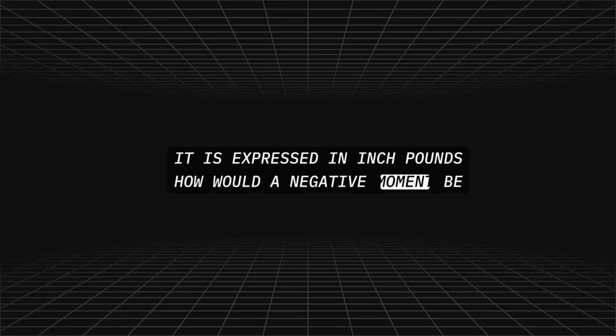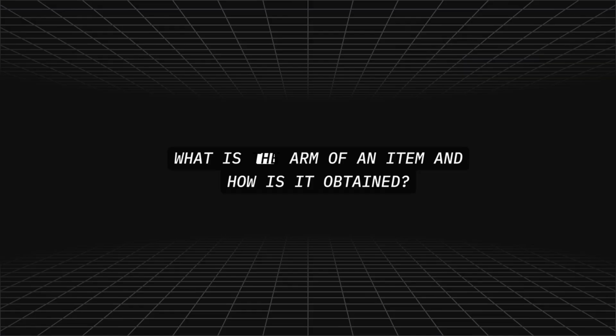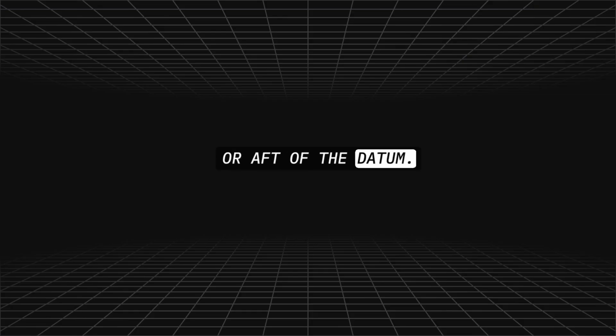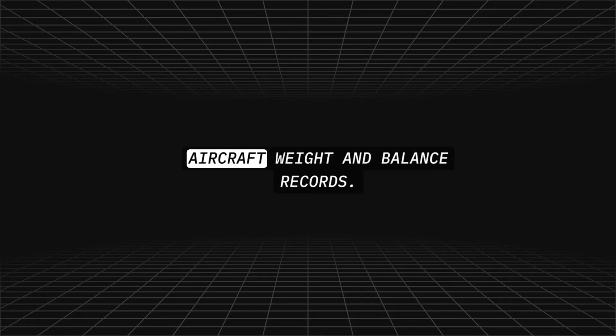How would a negative moment be obtained forward of the datum? By adding weight. What is the arm of an item and how is it obtained? The arm is the distance an item is located either forward or aft of the datum. It is obtained either by actual measurement or from the aircraft weight and balance records.